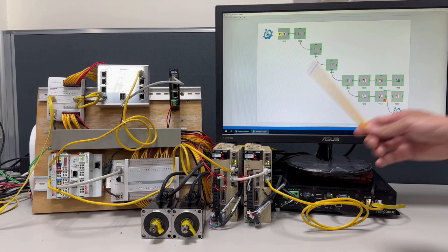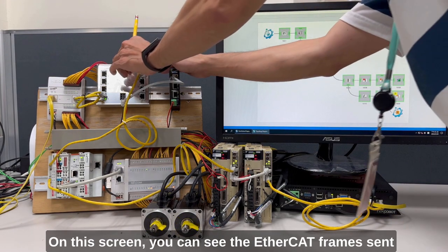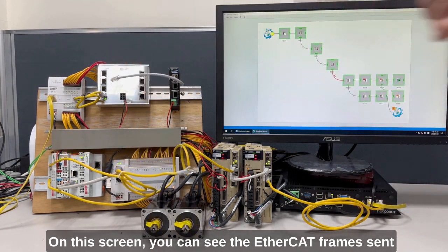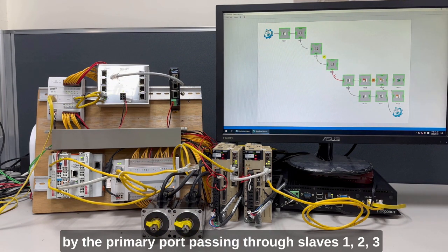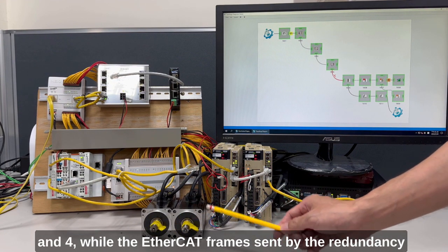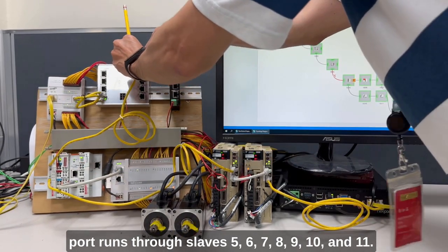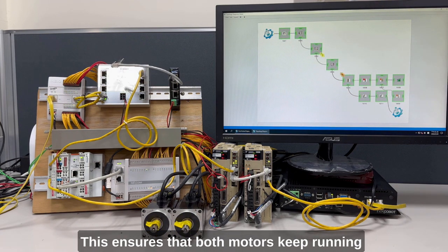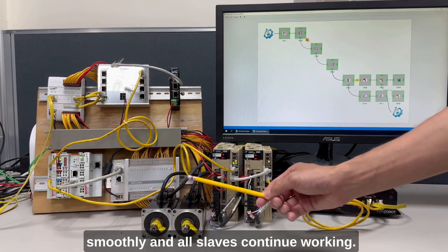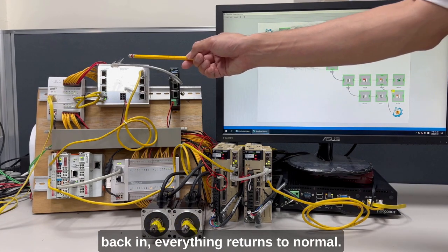Now let's unplug slave 5 from slave 4. On the screen, you can see the EtherCAT frames sent by the primary port passing through slaves 1, 2, 3, and 4, while the EtherCAT frames sent by the redundancy port run through slaves 5, 6, 7, 8, 9, 10, and 11. This ensures that both motors keep running smoothly and all slaves continue working. As you observe, when it's plugged back in, everything returns to normal.